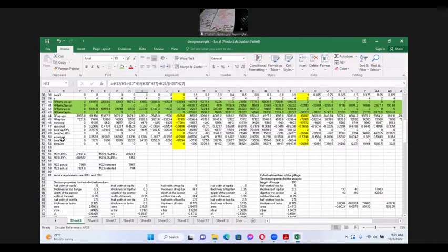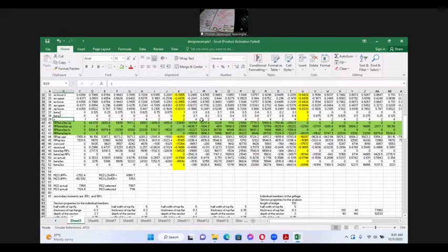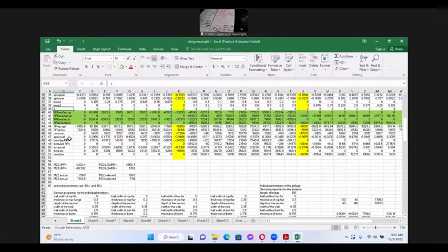So this is a method. And now you can see why I have this factor called S. Can you see why I have a factor called S on the spreadsheet? And then we use the same method, same technique to find all these different things. Because once you have the profile, then we know the actual EP and then we know the actual ES. If you look at EP actual, it will generate 0 secondary moments. And then ES actual will generate the assumed secondary moments. And you can see ES actual, due to these actual profile, actual values. These are the selected values. They are pretty close.